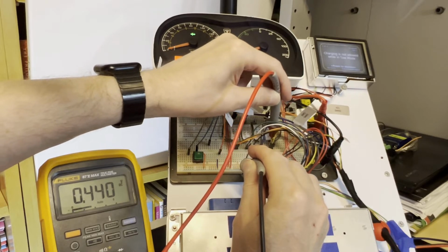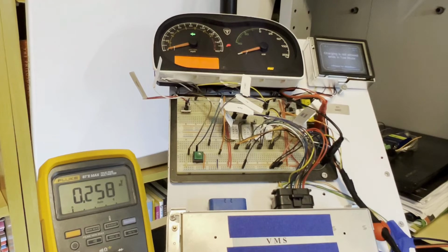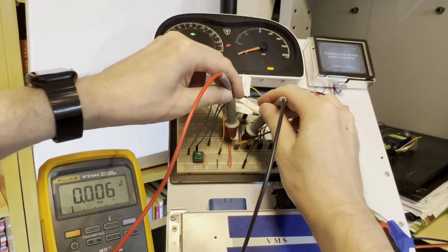This is expected. The CAN bus is a differential bus, with the difference between the 2 wires interpreted as the signal. When idle, we would expect 2.5 volts on both wires. When active, the high line goes to 3.75 volts and the low 1.25 volts, leading to a differential of 2.5 volts. Let's use an oscilloscope to look into this in more detail than a simple multimeter can allow us.